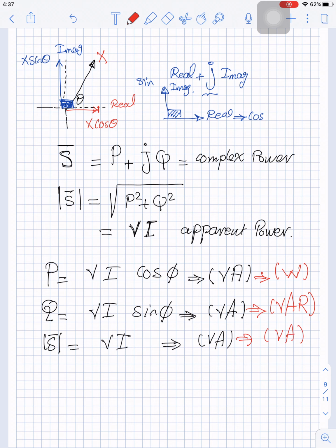So whenever we say we have a load with 50 watt, watt is the unit for the active component. So this is the average power. So how do you get the energy? Multiply this average power by time. And this is what they do at the meter you have at your home. The measurement is kWh, because this is the active component. So they will charge you for the productive power you consume, not the power going back and forth between you and the utility.